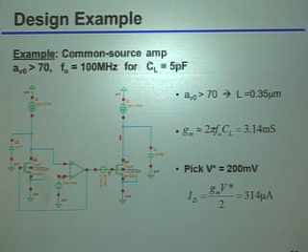So if you remember, I said that once you pick the V star, that's also implicitly setting the current density. So indeed, what I'm basically doing is saying, well, okay, I know how much bias current I need, so I'm going to feed that into the drain of this transistor here. And I don't really know exactly what the VGS is supposed to be, so I'm just going to use that same op-amp trick to fix the VGS based on the nominal VDS that I want to support.